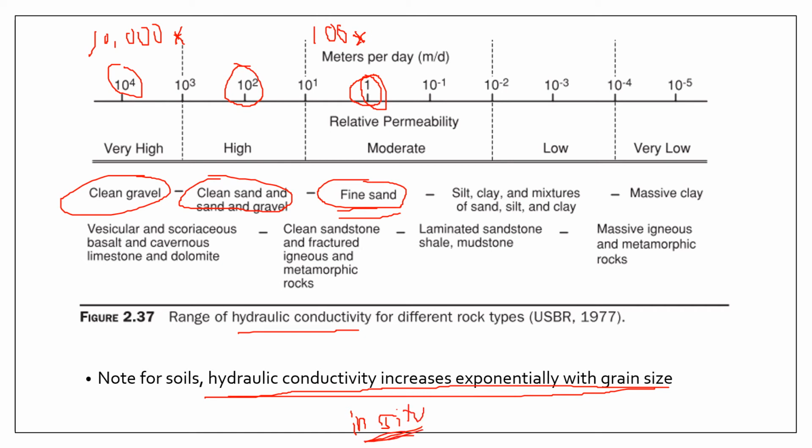All right, in situ testing like well tests, slug tests, and other field testing is very important in hydrogeology, because they more or less account for the variabilities in your aquifer conditions, unlike laboratory testing or using correlation tables. These correlation tables and lab testing can easily mislead you in terms of numbers.